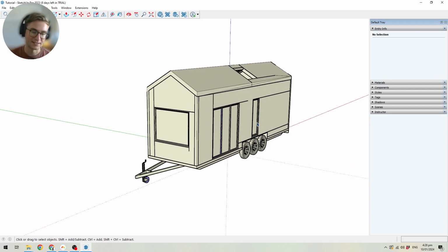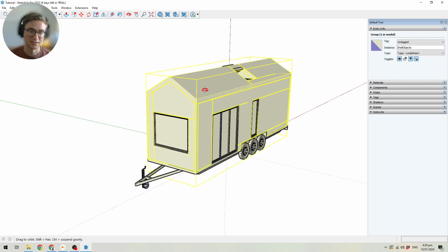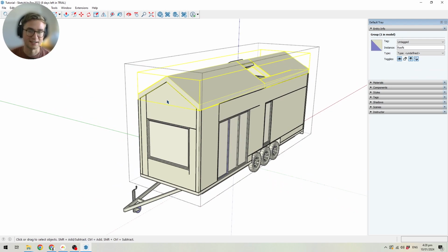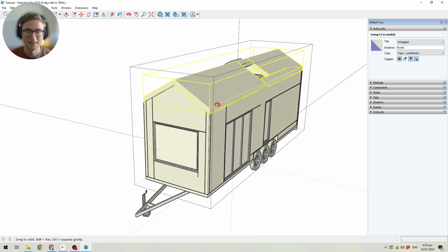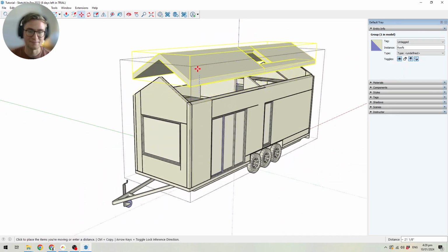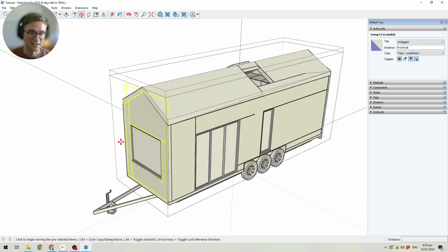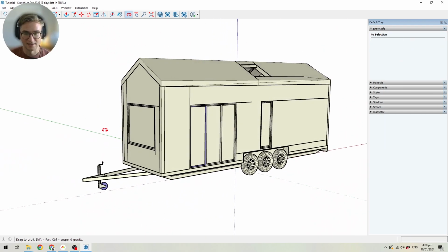The way that we have designed the SketchUp export is that the workflow is quite helpful in the SketchUp setup. So for example, all of the walls and windows are grouped separately, so you don't have a bunch of meshes sticking together, which you would probably know if you haven't properly grouped objects together in SketchUp before. So what you will see here, the roof, for example, is its own mesh. The walls are their own mesh. Each window has its own group like that, meaning that you are now able to start modeling in SketchUp quite quickly.